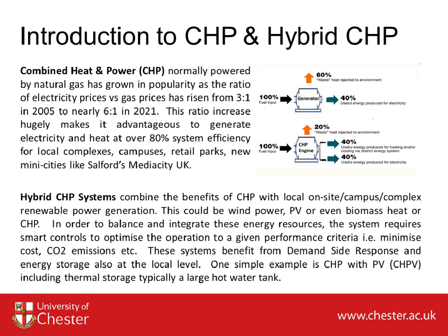That is all about generating electricity and generating heat. And the problem is that's only part of the equation. There's another efficiency, and that is how well you utilize it. So there's very little point in making electricity generation 50% more efficient if you're then going to power an incandescent light bulb which has an efficiency of 2%. If you used it to power an LED light bulb at over 90%, then you can see that the combined mix of utilization and generation is highly important.